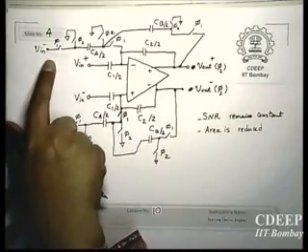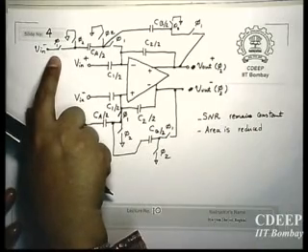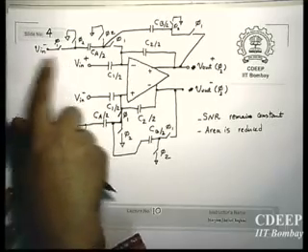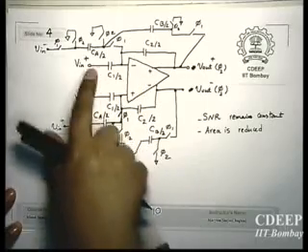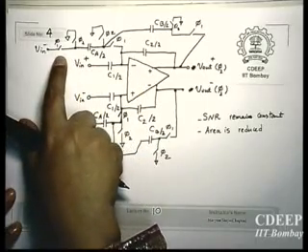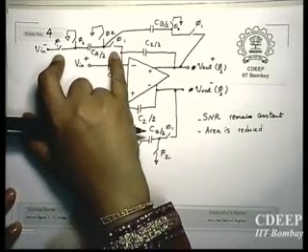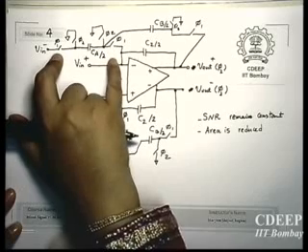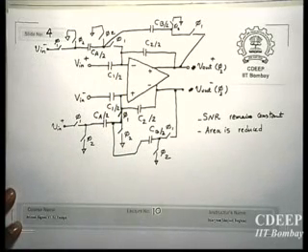If that also works with phi 1, you will have a series connection of this, which makes it difficult to control when you have many switches in the forward path. Phi 1 here, one switch is here. Now going to the next stage, again one switch over here, again one switch over here. Then you will have 4 series switches in the path, right?